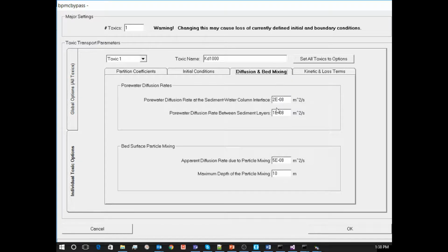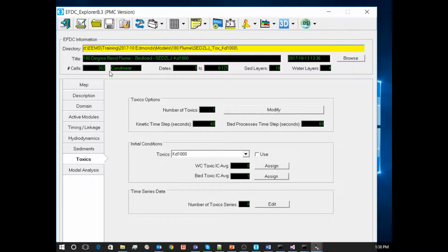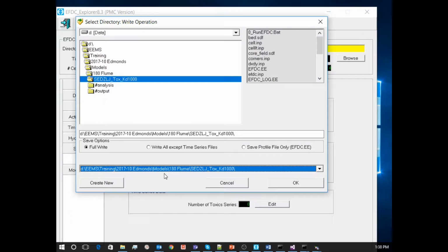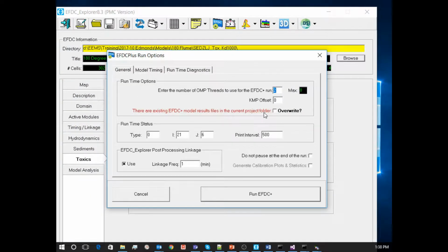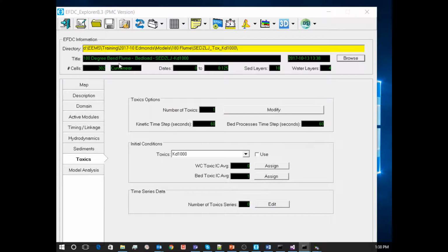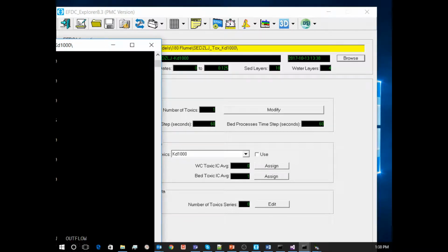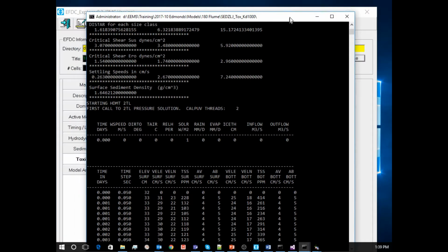I still left on all this. That's the problem. I'm trying to eliminate, doesn't really matter what I put here, but trying to eliminate the dissolved phase flow. Now that should hopefully make it look a little bit more like I'm expecting, because I had forgotten to turn off pore water diffusion.